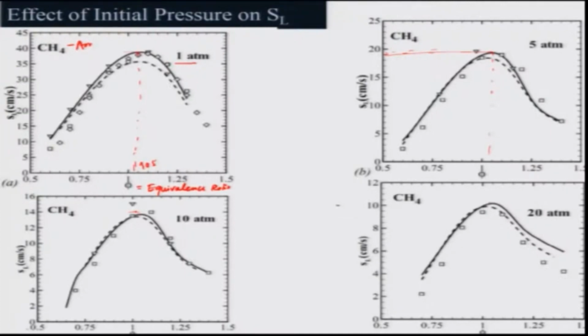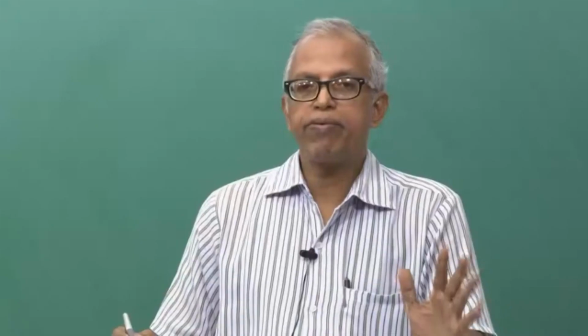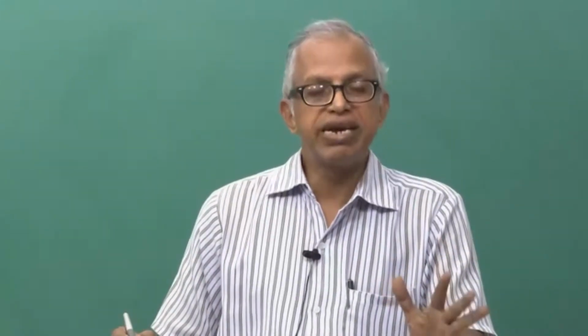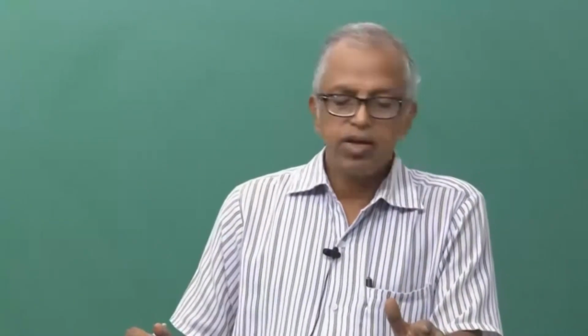Now, the question is why it is happening? With an increase in pressure, the laminar burning velocity is decreasing. In some cases, you may find that it is not really changing much. That is a different situation or a different fuel air system. But let us look at why the laminar burning velocity changes due to the change in the initial pressure.